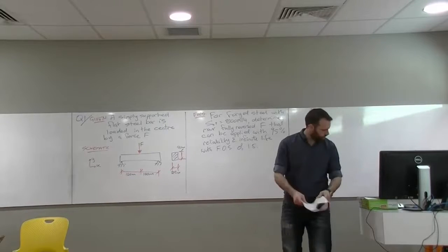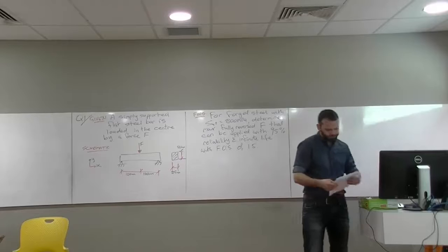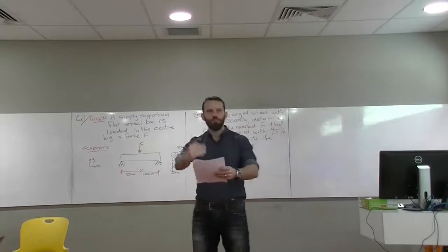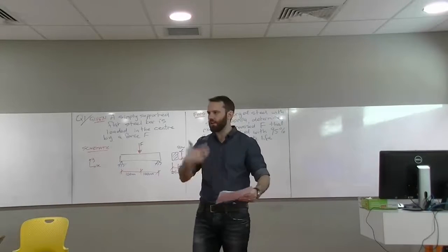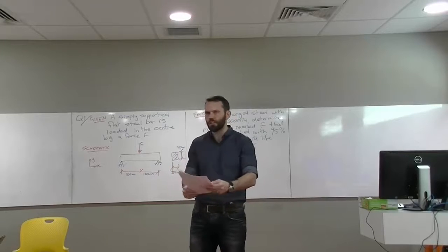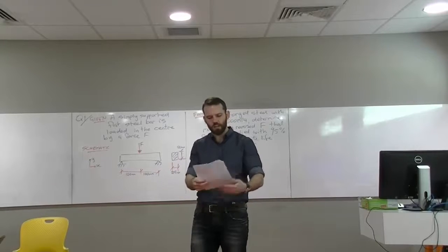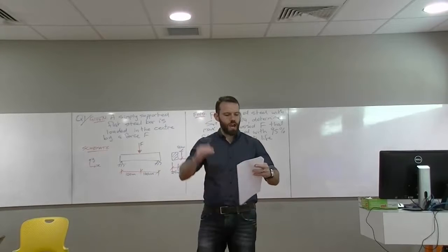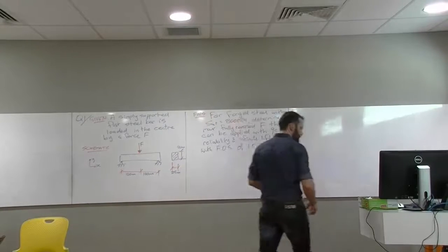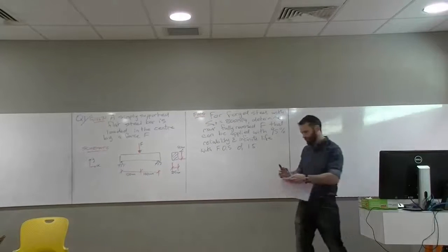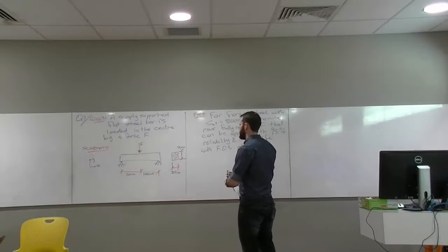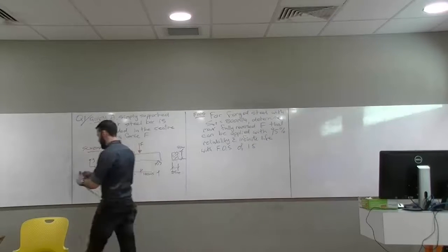You do all of your normal stress calculations first, so your free body diagrams and your stress elements and stuff like that, the first parts of the flowchart. And then I'd put a heading for endurance limit.